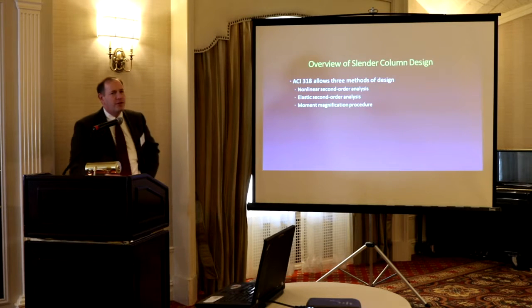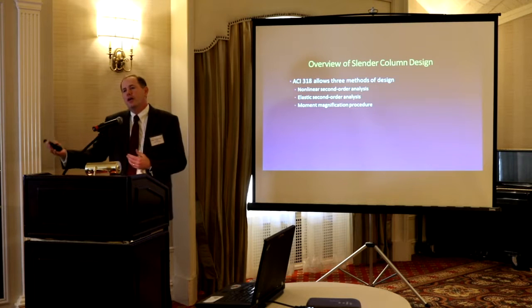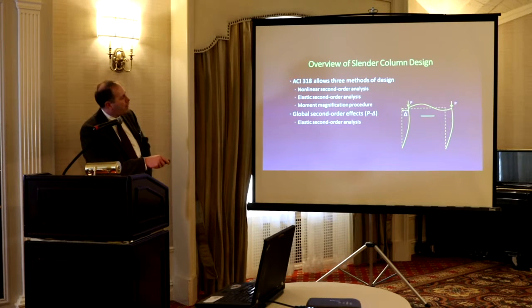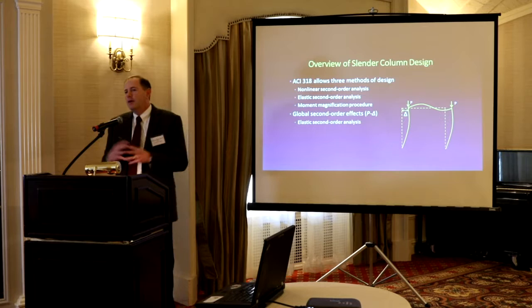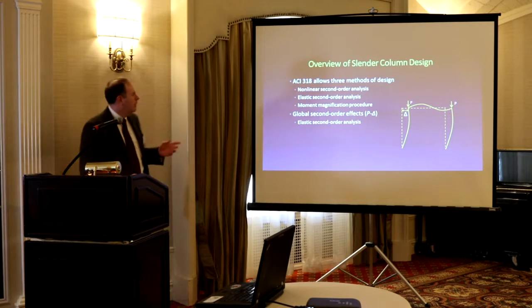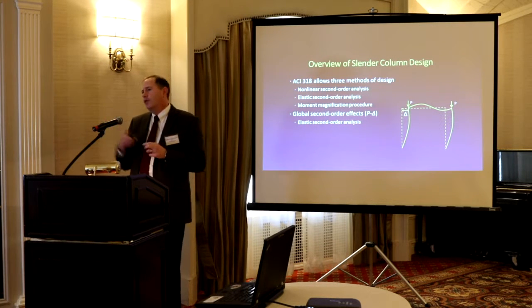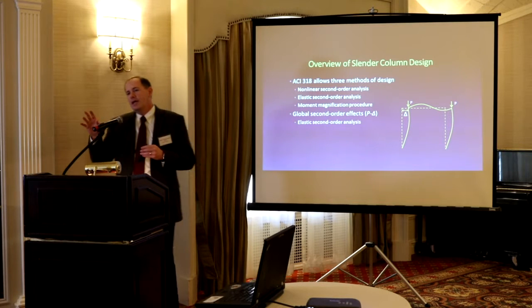And then there's moment magnification procedures, where I do an elastic analysis and take a magnifier to increase those moments. So if I have global second order in a frame, I get a deflection laterally here, and this is the big P delta. So we're getting second order effects from that sway of the frame. Elastic second order analysis picks that up. Great, right? Most programs default to that now. You can put a checkbox on some that will run that, and so you get those forces.